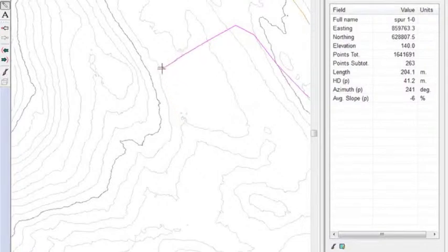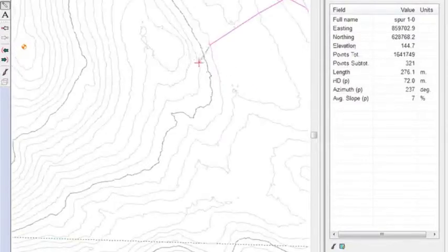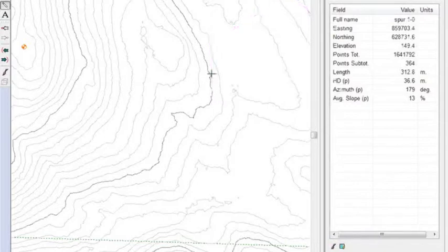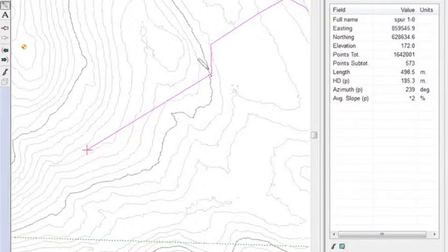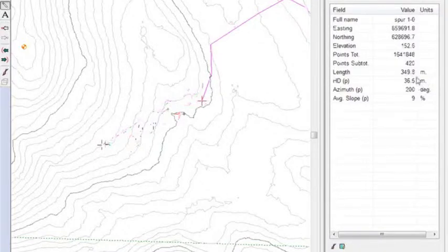Okay, back up the other side. Let's sort of go over to here, so we've got some room to start pegging. And now I'm going to start going up the hill. 27%. Let's try and keep it around 12 if possible. 13, that's reasonable. 12, okay, there we go. And then we'll go along here. Now I could just jump along like this until I get 12%, but I think you're going to need more curves in here. So I'll go back and do shorter legs.